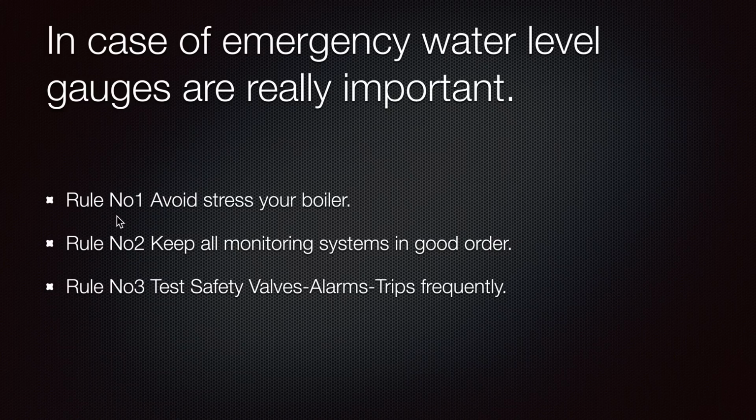And if the water is too low inside the boiler, structural damage can happen, because the tubes will be exposed to excessive heat and the tubes will be deformed.